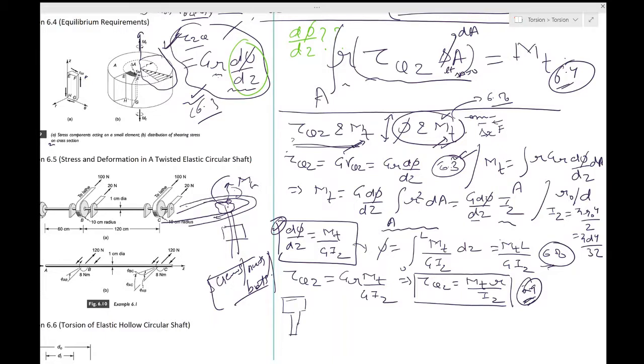And that's why I always insist, and you should always do it yourself, to stay away from the boundary as much as you can, so that even when the actual loading is different from what you have idealized, your answers would still be correct about finding the stress, the strain, the displacements or the twist.